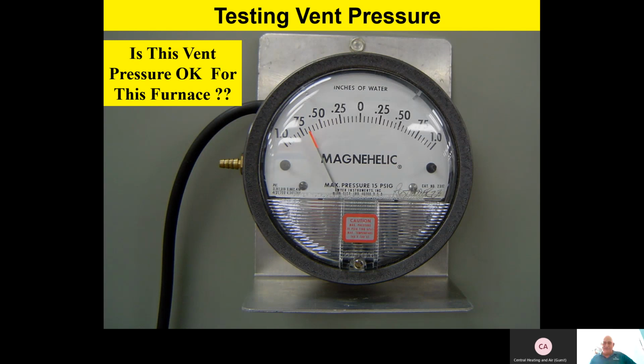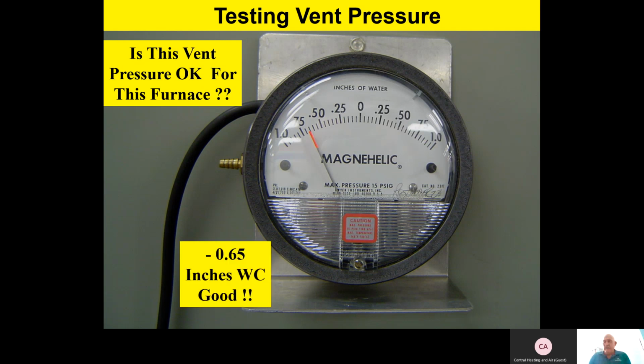So here we go. In this second example, we see it's maybe a different furnace or what have you. But in our example, we needed a negative 0.5 to close the switch, and in the second example, we see we've got about a negative 0.65. So the furnace is operating. Maybe this is a little different service call where we have a longer vent pipe, or maybe an extra elbow in the vent pipe or what have you. So it's a little different pressure.